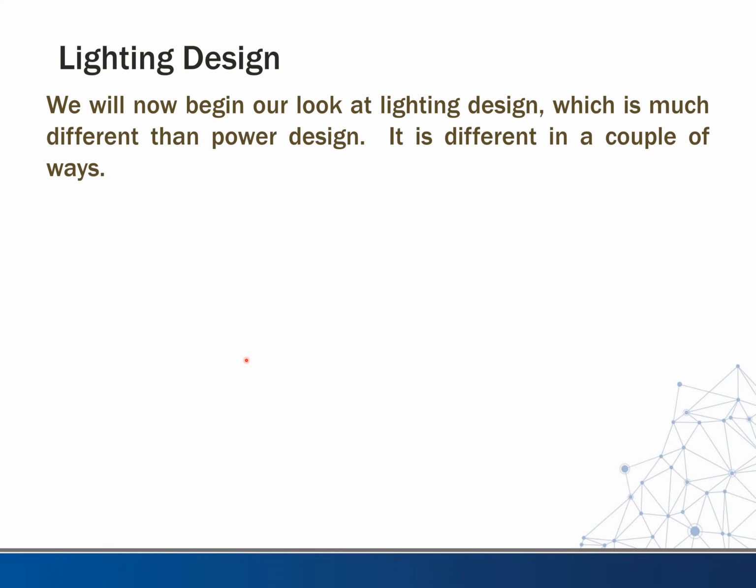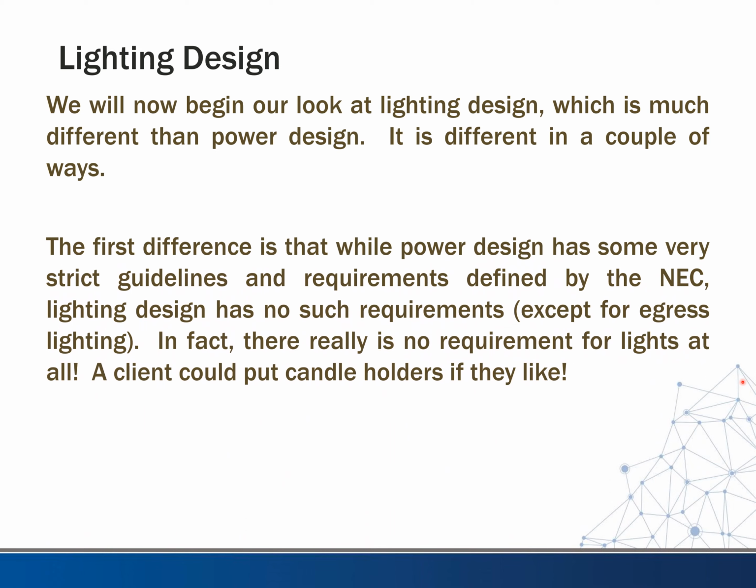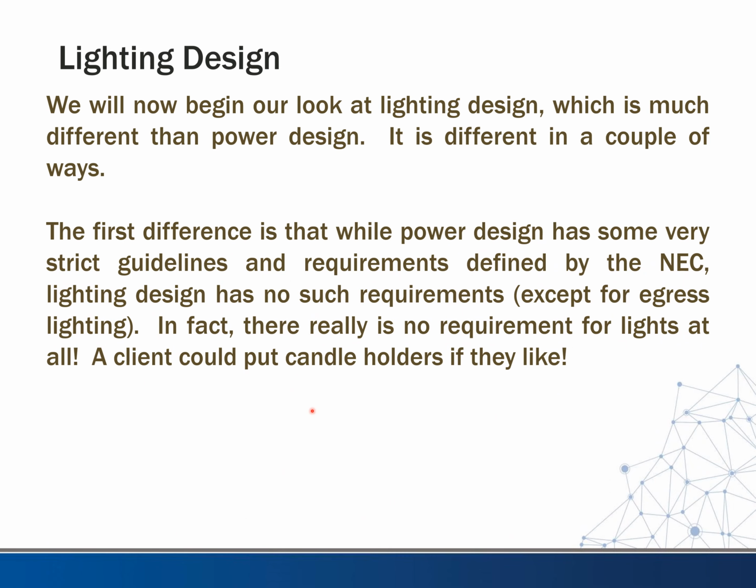So we'll now begin our look at lighting design, which is much different than power design. It's different in a couple of ways. The first difference is that while power design has some very strict guidelines and requirements defined by the NEC, lighting design has no such requirements, with the possible exception of egress lighting. In fact, there really is no requirement for lights at all. A client could put candle holders in their building if they like.